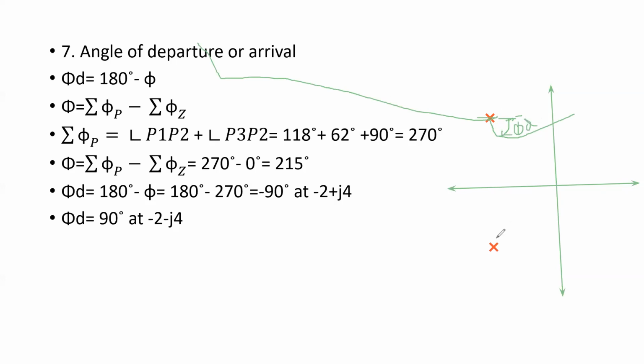So this will also have an angle. We had a pole here and we had one more pole at -4. Now what is the angle this pole makes with this? What is the angle this is making? This is around 118.